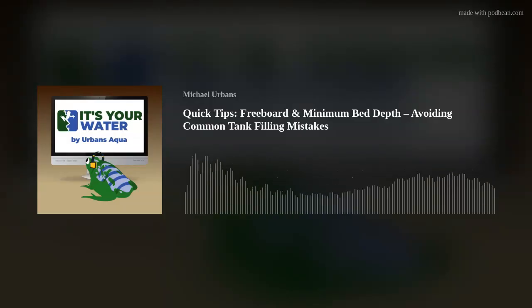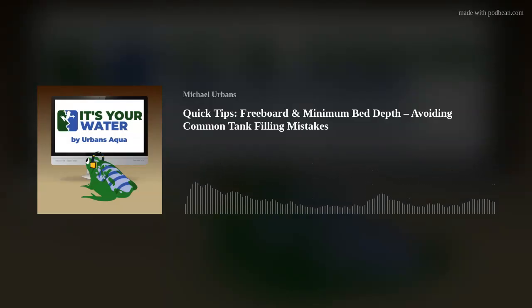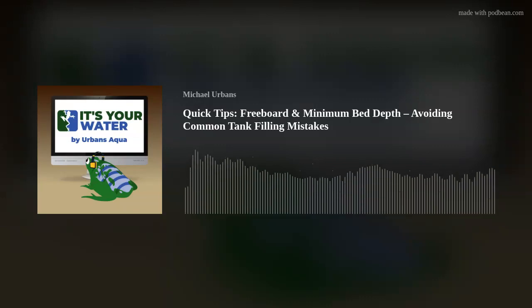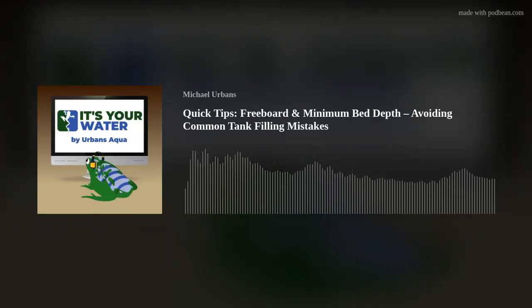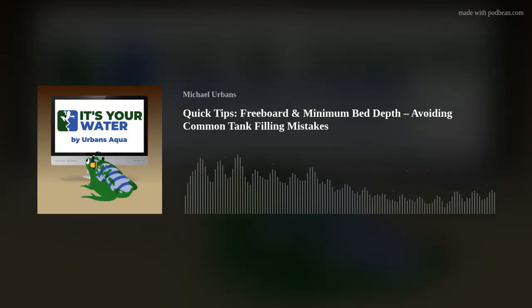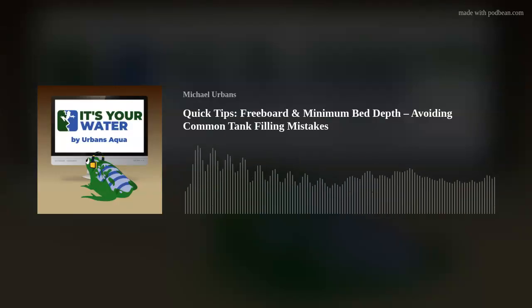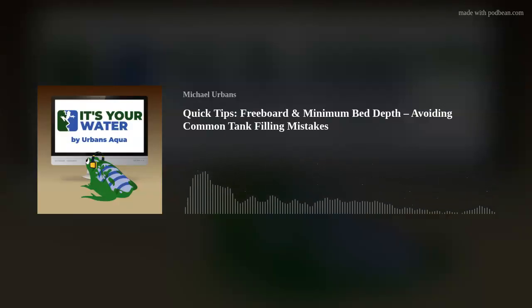And upper screens also act as a diffuser through the bed. I like them because you diffuse the water path more evenly through the resin. If you flip a valve over, next time you do a control valve, backwash valve, flip it upside down, and you'll see it's like a half moon input. You have your distributor tube pilot, and then like this half kidney bean half. That's your inlet flow. Well, that's going to drill. If you're flowing real hard, that's going to kind of come down.